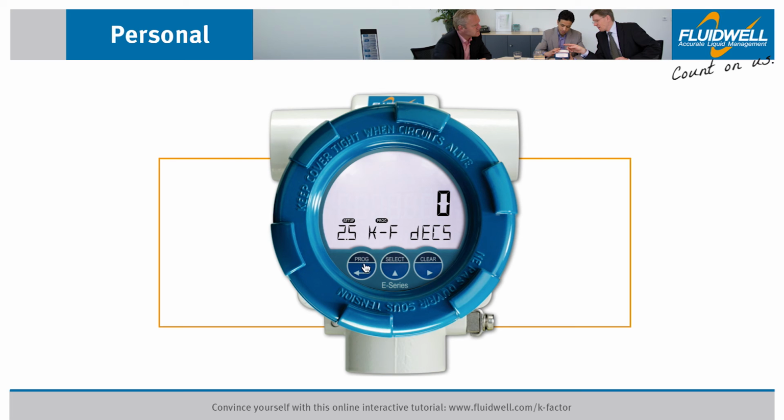In this example, our K-factor has 5 decimals, so we have to set the K-factor decimals to 0.00005. Press Prog to store this setting. Press Clear to go back to Menu 2.4 K-factor. You will see that the decimal point has been set and the K-factor is now 25.07705. Next, we're going to set the flow rate calculation factor. Press Select to go to Menu 2.6 Calculate.